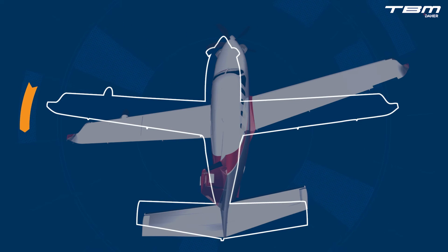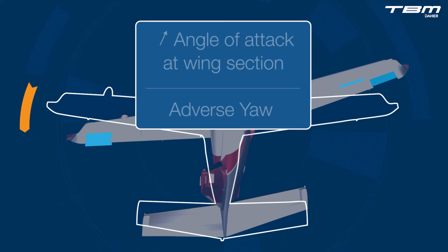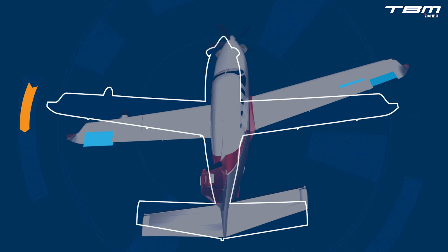Earlier we mentioned that the primary flight controls used to roll an airplane were the ailerons, which is true. Unfortunately, ailerons have two byproducts which are undesirable when flying at minimum controllable airspeed. Ailerons increase angle of attack, and they produce adverse yaw. On all airplanes, the lifting aileron increases the angle of attack at the associated outboard wing section. Lift is manipulated to roll an airplane.